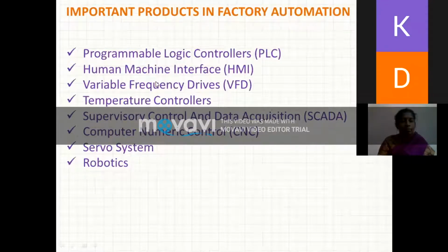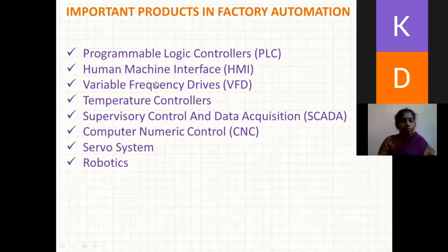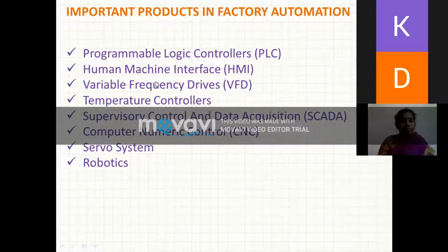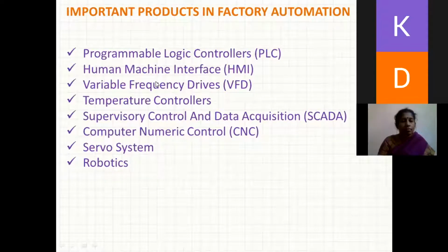You know about induction motors, DC motors and everything. In college laboratories, we would have conducted some experiments by connecting directly to a three-phase supply. But in industries, they connect the incoming supply to a VFD. These VFDs in turn give the power supply to the motors. What happens inside a VFD is that it converts AC to DC and again DC to AC.